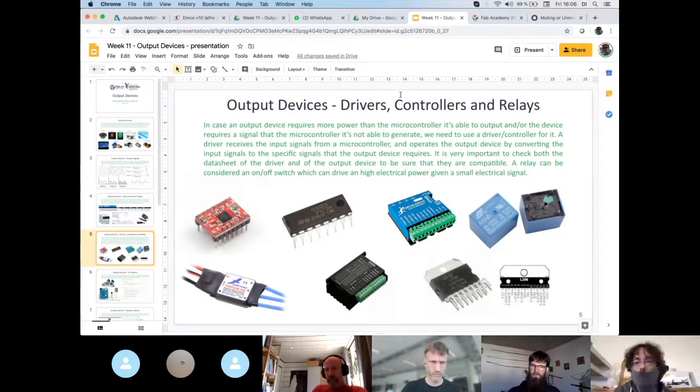These are for stepper motors. The servo motors we control. So that you showed us for the brushless motor. You showed us for a servo motor, and for the DC motor, you haven't shown us here a controller for a DC motor. For a DC motor, you can use a relay just for fixed speed, or you can use a transistor or a MOSFET. Now, do I use a PWM for that, or do I just adjust the voltage that goes to the DC motor?